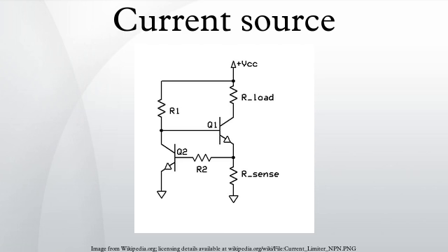The internal resistance of an ideal current source is infinite. An independent current source with zero current is identical to an ideal open circuit. The voltage across an ideal current source is completely determined by the circuit it is connected to. When connected to a short circuit, there is zero voltage and thus zero power delivered. When connected to a load resistance, the voltage across the source approaches infinity as the load resistance approaches infinity. Thus, an ideal current source, if such a thing existed in reality, could supply unlimited power and so would represent an unlimited source of energy.